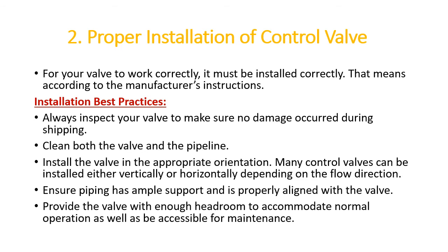The control valve should not be installed when blasting or cleaning of the line is pending. There have been situations where the control valve is installed in the line and sandblasting is going on, and some cleaning of the pipe is going on. This is a very bad thing, because the sandblasting and cleaning of the lines definitely have the potential to damage the internals of the valve. So always avoid installing the control valve before the cleaning of lines.